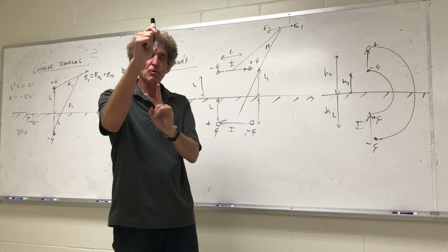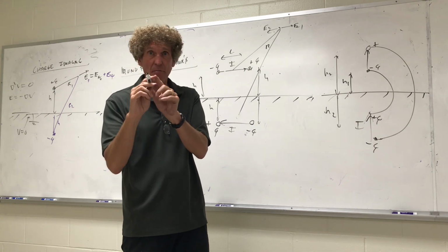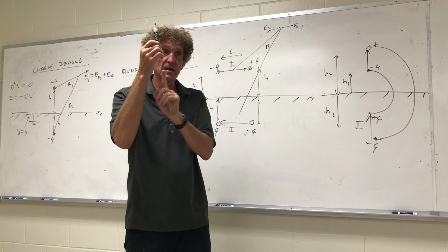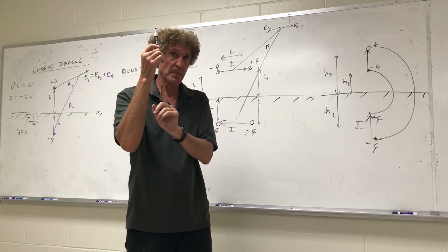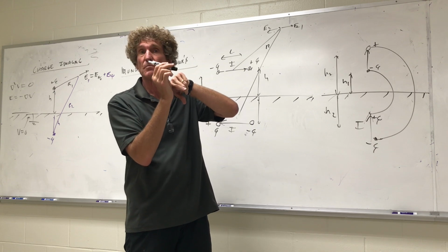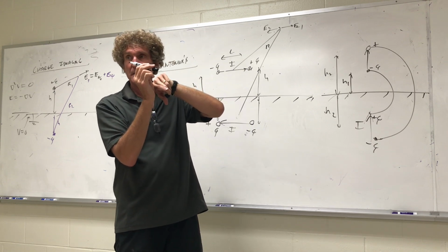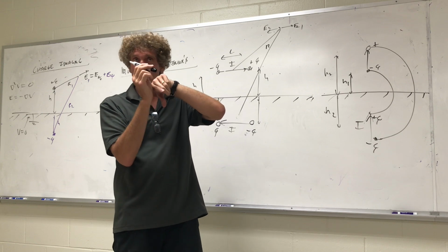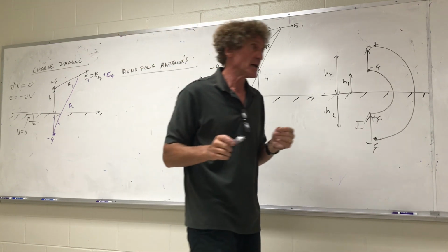Therefore, currents that are perpendicular to a conducting ground plane image, the images are in the same direction. If they're parallel, they're in opposite directions. And in EMC, this is real important. Electromagnetic compatibility and radar and probably some designs. It's very important to understand that.